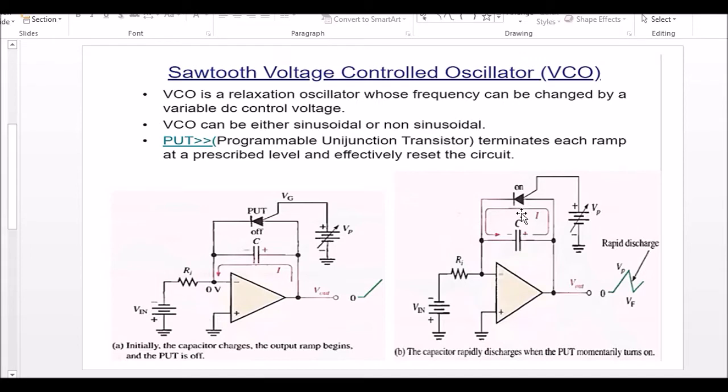So at that stage when your diode is triggered on, or your circuit turns on, your capacitor starts to discharge via the circuit. So your V out suddenly drops because of this discharge current. Your output voltage is suddenly dropped, right? So this dropping produces that sawtooth waveform, right?